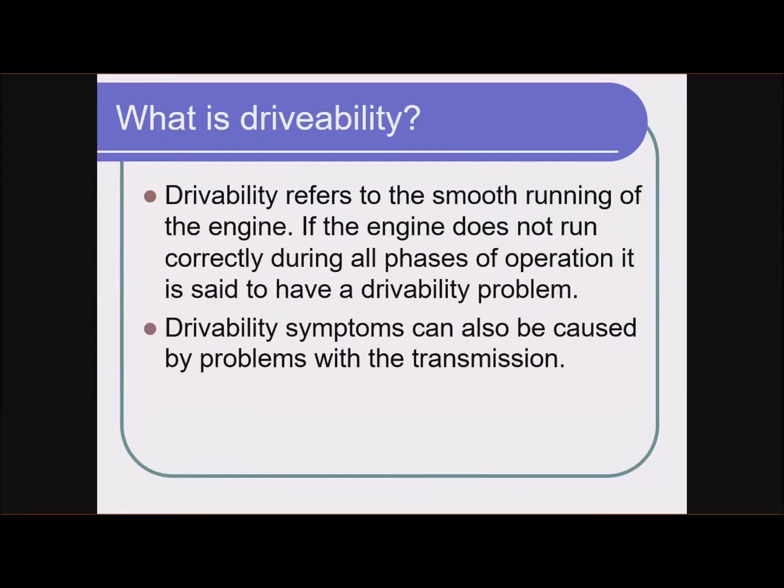Obviously, if you have flat tires or things like that, it does affect the way the vehicle drives, but we don't call those drivability problems. We would call those suspension problems, steering problems, brake problems. Drivability is really about how the engine runs. There's a set list of symptoms that we call drivability symptoms, and I'll list those in a bit. It should be noted here that some symptoms can also be caused by problems with the transmission.